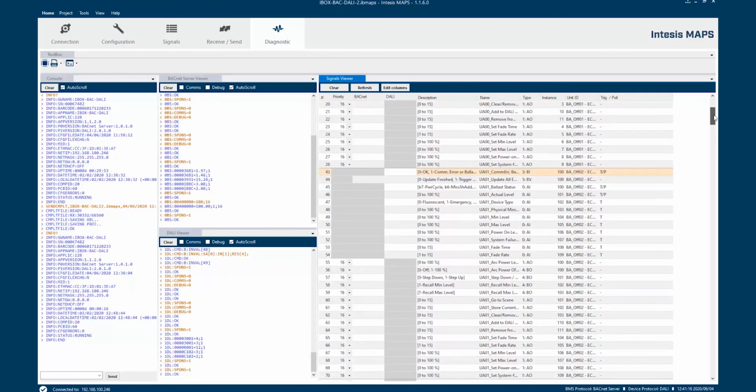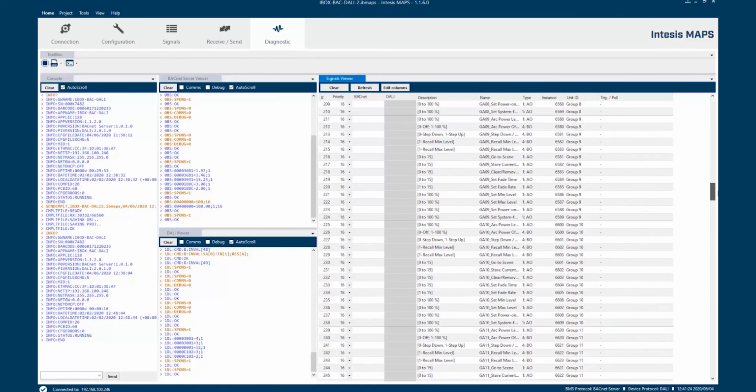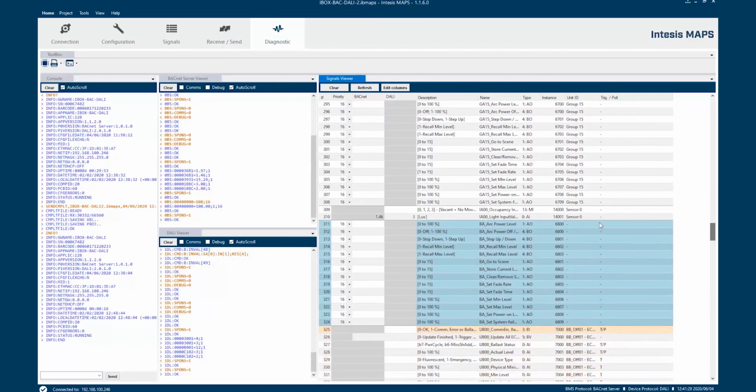This is for all the devices, but we can also trigger some group signals. So in order to make sure that we can control more than one, or perform broadcast actions as well to trigger light levels, or to ask information to the DALI bus on a broadcast level.